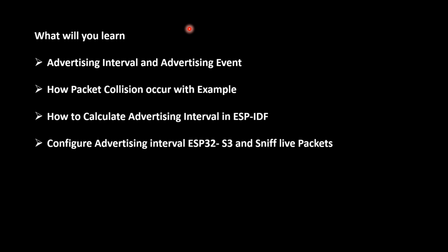ESP-IDF has provided a formula to calculate the advertising interval. This calculated advertising interval we will configure using an ESP32 S3 development board and sniff live packets, and we'll check that the advertising packets are transmitted as per the set advertising interval time. So stay tuned, and